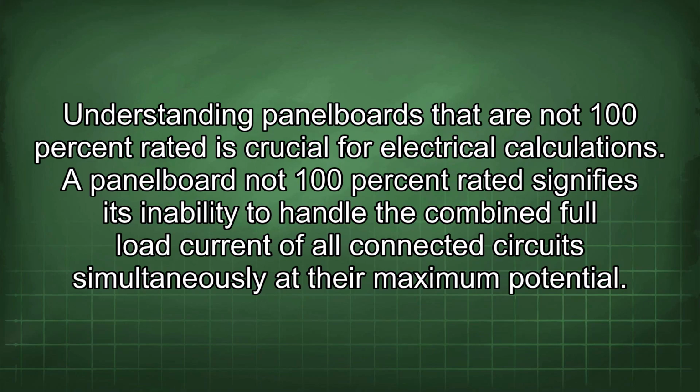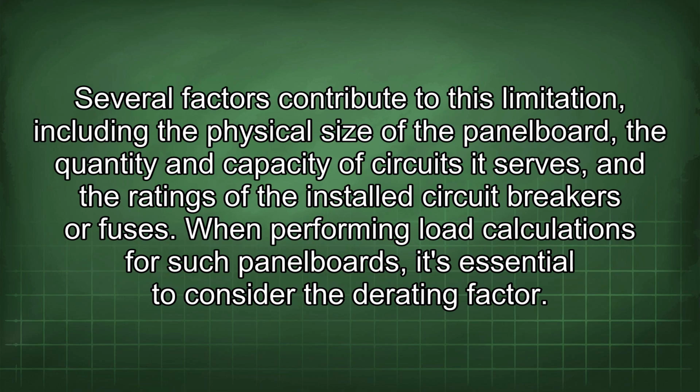Understanding panel boards that are not 100% rated is crucial for electrical calculations. A panel board not 100% rated signifies its inability to handle the combined full load current of all connected circuits simultaneously at the maximum potential. Several factors contribute to this limitation, including the physical size of the panel board, the quantity and capacity of circuits it serves, and the ratings of the installed circuit breakers or fuses.